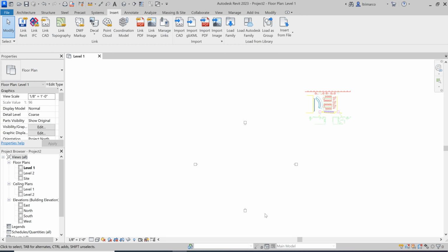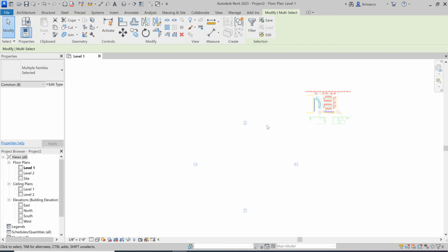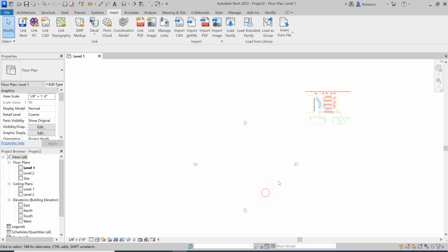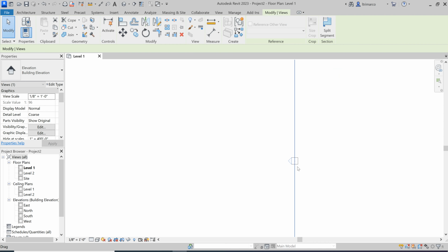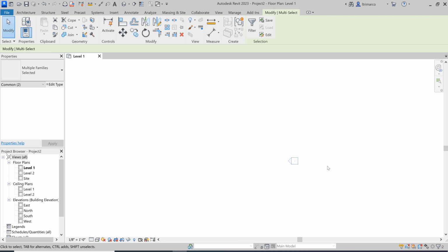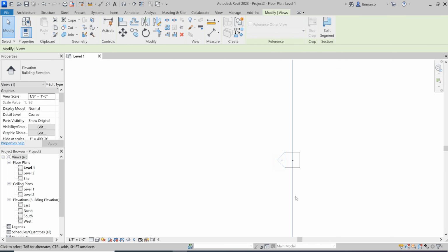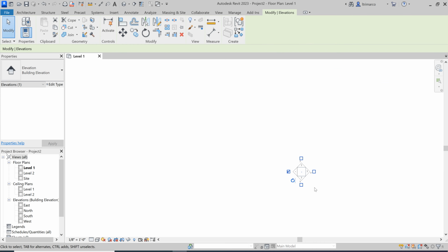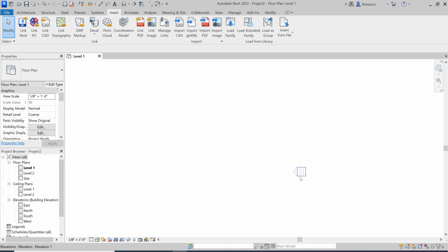And I'm just going to select them all, window selection, either a crossing window right to left or left to right, just like we would in AutoCAD. The reason why I'm doing a crossing window is I just want to make sure that I select all the parts and pieces. If I go ahead and snap, you can see that if I don't hold down the control key, I could be selecting the tip of the tag or the base of the tag. And I'm not ready to explain the details of it, but we are going to go there. Instead, I'm just going to select a crossing window.